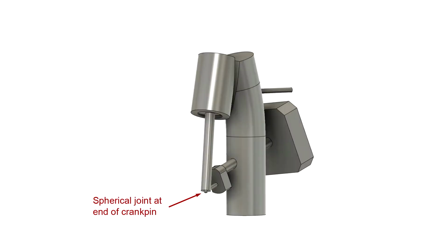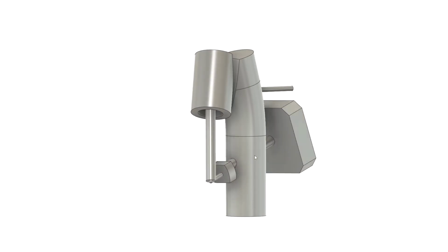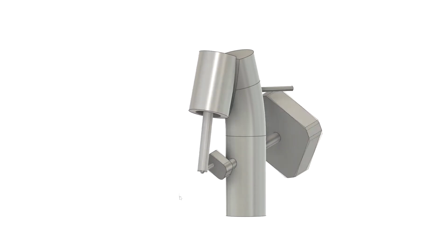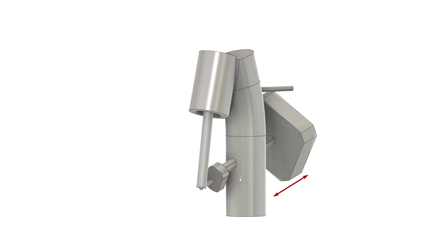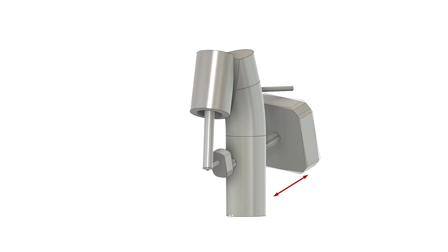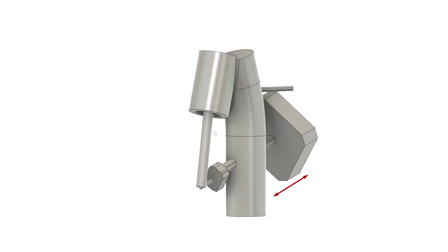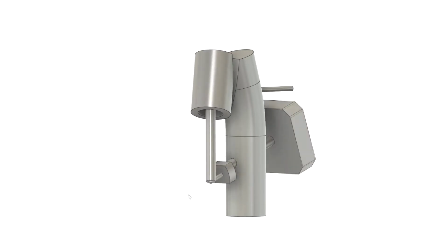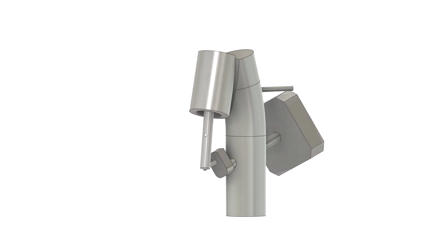Clearly the rod end joint must relax some degrees of freedom, so let's try a spherical joint at the rod end, fixing it axially on the crank pin. It works, but things are a little strange. The crankshaft has to slide axially for a kinematic solution through an entire revolution. Imagine the vibration of an engine with a heavy flywheel pumping back and forth like this, not to mention the added friction loss in the axial bearing. Also note that there's some interference at the spherical joint.